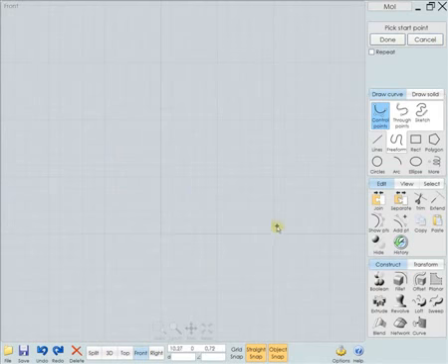And in order to start exactly on this line here, I'm going to create what's called a construction line. I'll go to the origin where I have a snap point. I'm going to click and hold down the mouse button and drag to the right. This creates a construction line when I then release over here. This kind of construction line can be used for additional snapping to create alignments, extensions, all kinds of things like that.